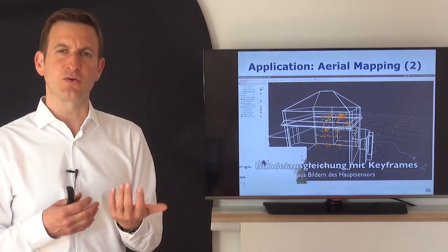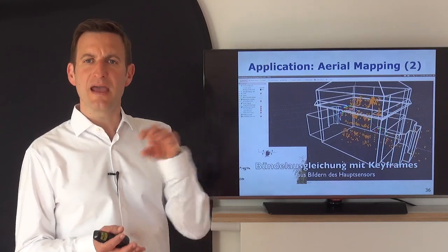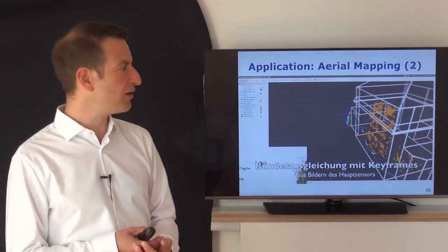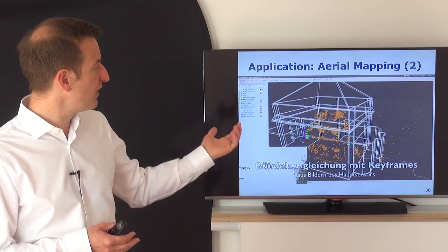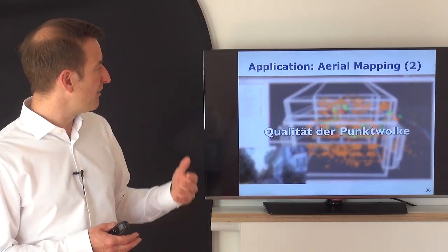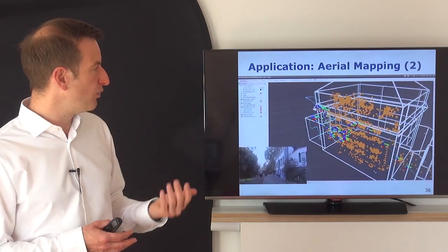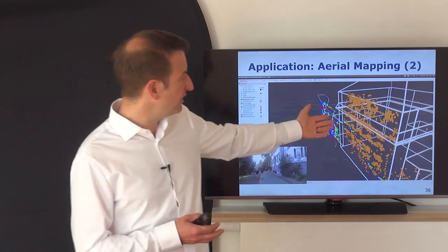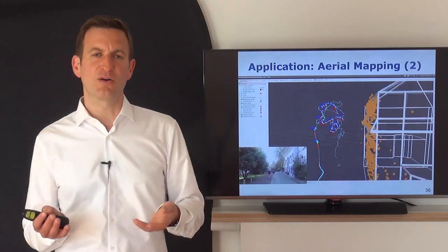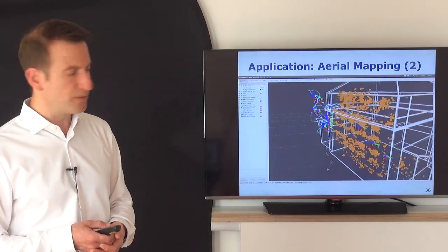And what runs here is a so-called bundle adjustment approach, which is a least squares approach for estimating the camera location as well as the location of distinct points in the environment, which then allows us to provide, after some optimization, a full point cloud of the scene, which I can also compare to a high-resolution 3D model and can see that those points are very close to the original model, typically with errors of 1 to 2 centimeters possible to obtain with those UAVs.